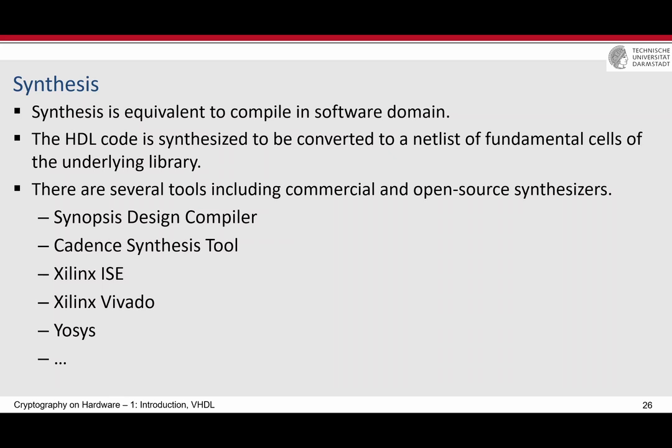But of course, you can check whether the code that you have written is synthesizable, I mean, by ISE and also Vivado, and also you can check the functionality. Yeah, simulation you can do, but of course, the behavioral level simulation. For synthesis, if you want to target ASIC, then ISE and Vivado are probably not the best choice.